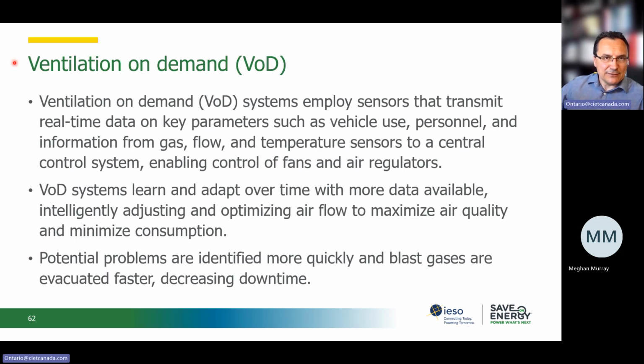Ventilation on demand is one of the strategies we apply in our systems for improving the efficiency of HVAC systems in our buildings. Designing systems is based on the principle of being able to provide the service at worst case scenario type of conditions, and ventilation on demand is a way to achieve savings when the system is not at full capacity, it's not required to operate at full capacity.